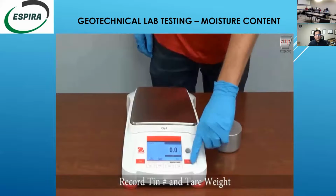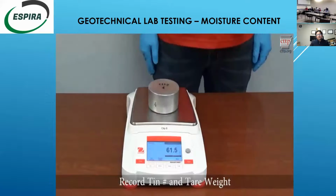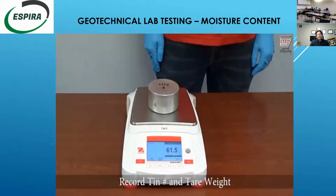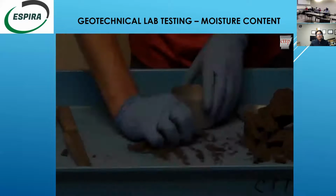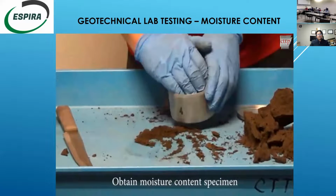Zero the scale and place a clean, dry sample container with the lid on the scale platform. Record the tin number and the tare or empty weight of the container, including the lid. Obtain a representative moisture content specimen and place it in the sample container.